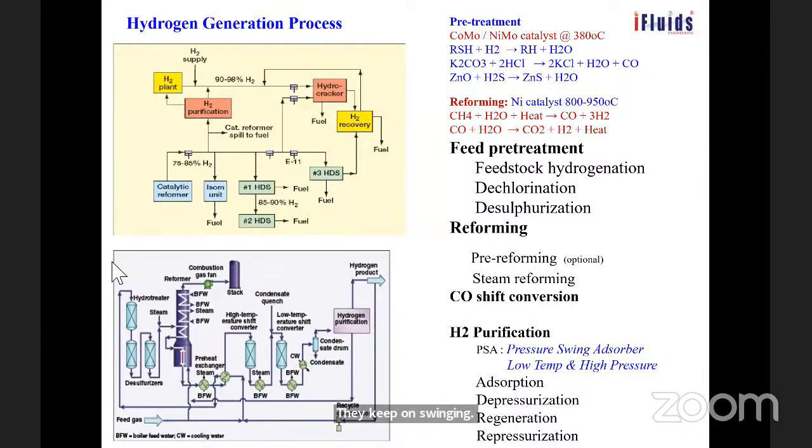And when you go through this process, you can clearly see whatever I explained. All these things are in the diagram, and distribution also is given at the top. It is going to various units, hydrocracker and other units. They are distributed to the isomerization unit, catalytic reformer, all these places. And another thing is, this hydrogen coming out may be at 36 kg pressure. But some plants may call for higher pressure, so they use a hydrogen compressor. So the pressure is increased to 90 kg, depending on the requirement.